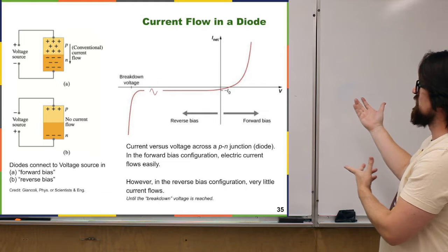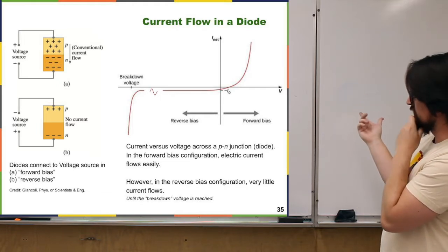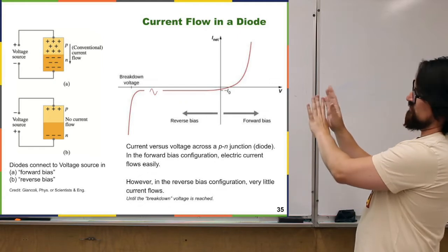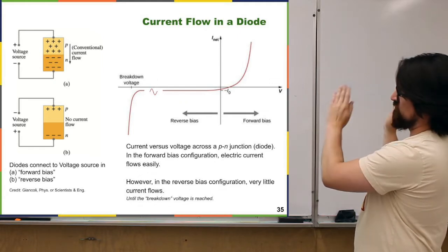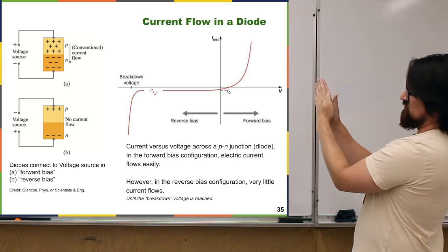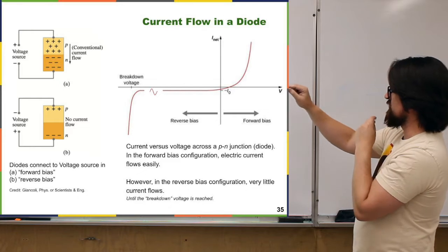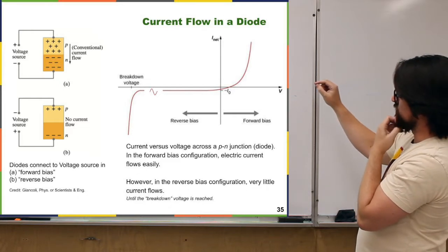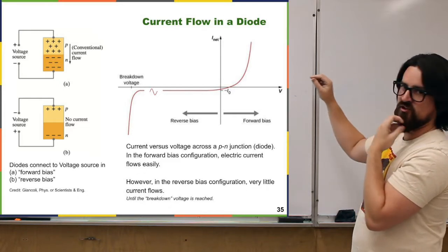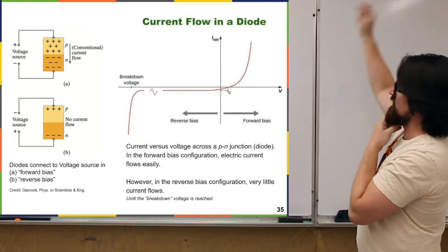And if you plot the voltage you apply to this diode against the current, at least for normal voltages, where it's not super negative and up to this positive side, you essentially get very, very little negative current flowing. Then if you increase the voltage to a positive voltage, and not necessarily even a very large one, your current just shoots up with this sort of exponential growth.